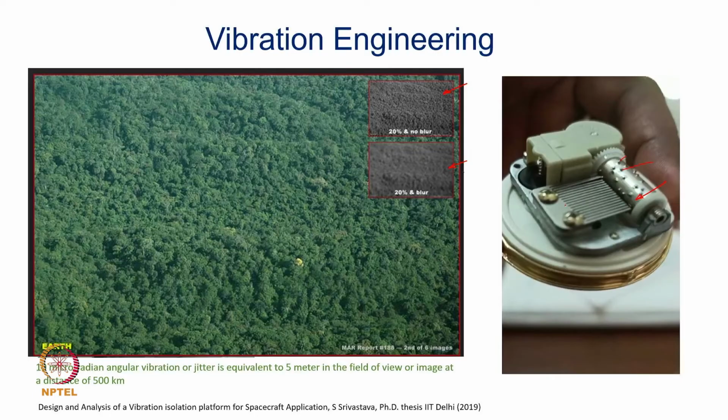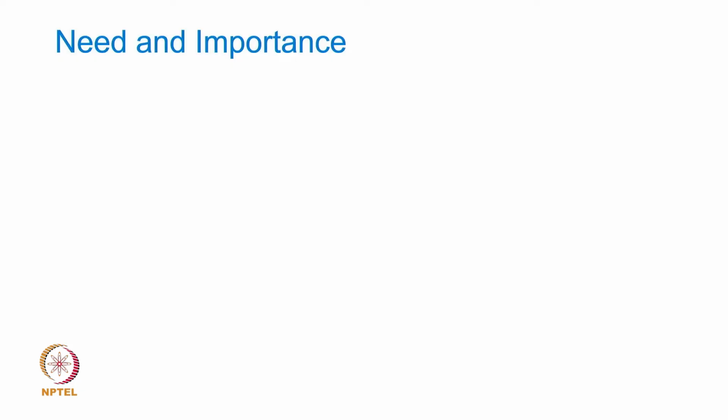And if you notice clearly, these cantilevers have different lengths, and depending upon the length of that cantilever, the frequency is generated. A specific sound of a specific frequency is generated based on which particular cantilever is excited. So, this is how a vibrating cantilever essentially generates sound of the desired quality, and that is how we design this vibratory system to generate specific sound. Okay. So, these are a couple of or three different application examples that I highlighted here, which tells you a wide gamut of application of the vibration phenomena.